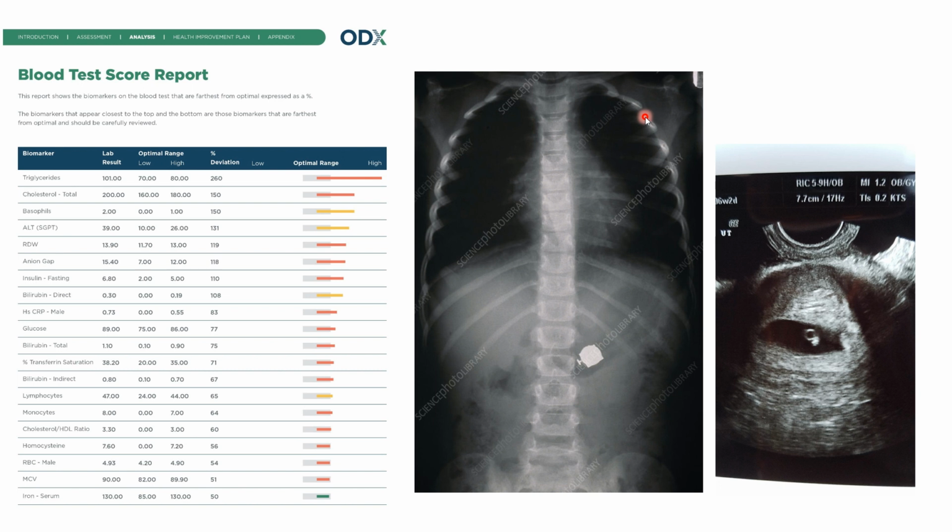Similar to that, we also bring the soil, we test it in our lab, and we give a similar report. Okay, this soil has a high amount of clay, or this soil is having some issues, or it can have some sulfate contents, chemical contaminations can be there. So we also analyze. You can see this is an X-ray of a person with a watch inside. Similarly, okay, there's a fault zone in your area.